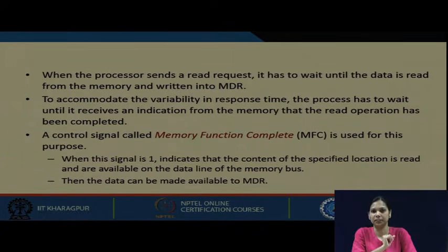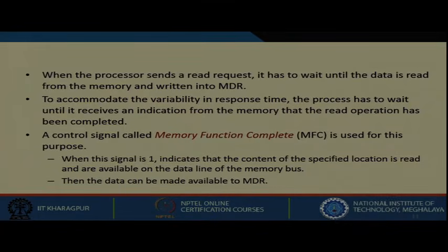For a read operation, we put the address from where we need to read into MAR, and we activate the read control signal. Now, we really do not know at what time the data will be available, but it will be available after some time. So, till that time the processor has to wait, but when will the processor know?